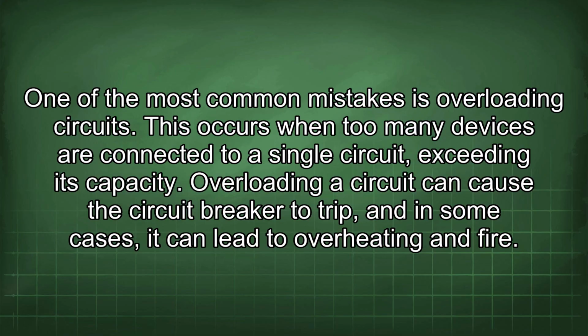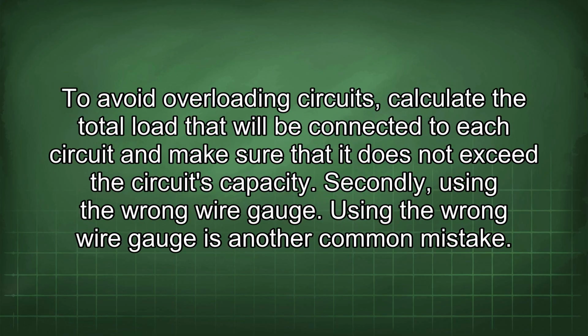Overloading a circuit can cause the circuit breaker to trip, and in some cases, it can lead to overheating and fire. To avoid overloading circuits, calculate the total load that will be connected to each circuit and make sure that it does not exceed the circuit's capacity.